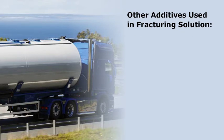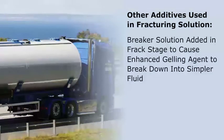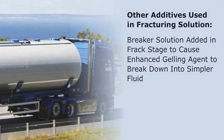When cross-linking additives are added, a breaker solution is commonly added later in the frac stage to cause the enhanced gelling agent to break down into a simpler fluid so it can be readily removed from the wellbore without carrying back the sand proppant material.